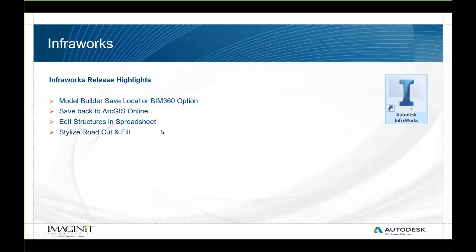Outside of that, we've got a slightly updated stylization for road cut and fill. Whenever you're dealing with component roads and you've got cut areas and fill areas, you now have the ability to apply different styles to cut areas or fill areas, to color code them or highlight them a little bit more in your models. And these can be done for each road, so it's not one style for cut and one style for fill only. You can select the road and actually choose the cut style and the fill style independently inside of your model. And for that, we have another example.